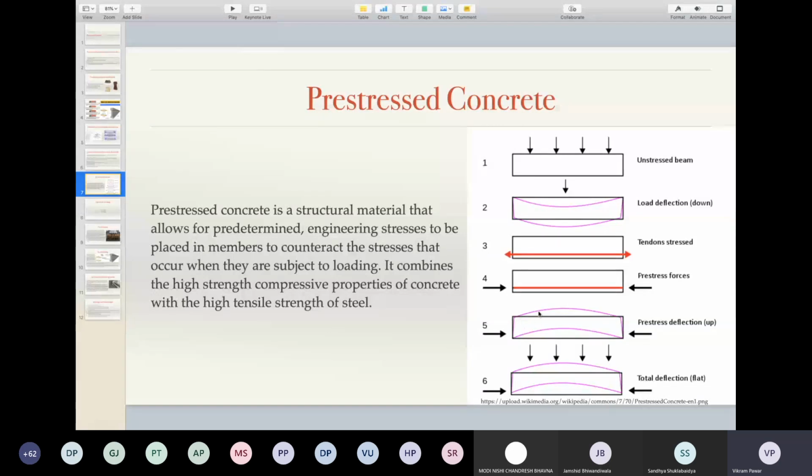Okay, this deflection, because of the high strength concrete, and this is also coming because there is a gravitational load. Obviously this is not going to fail, because this is carefully modulated so that it just is able to take care of its own self load. When the actual load applies, this beam is again going to flatten out. Okay, so conceptually it's going to flatten out.